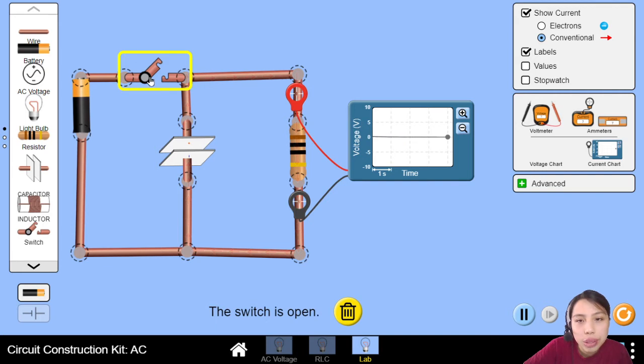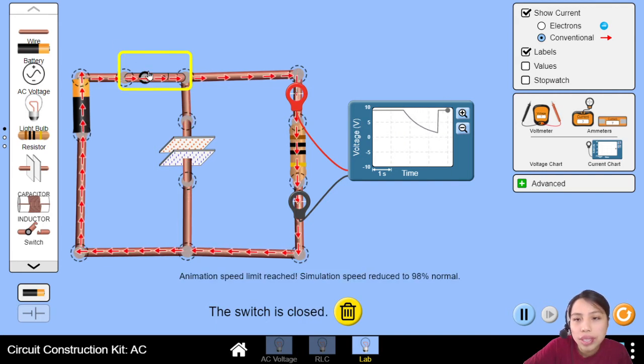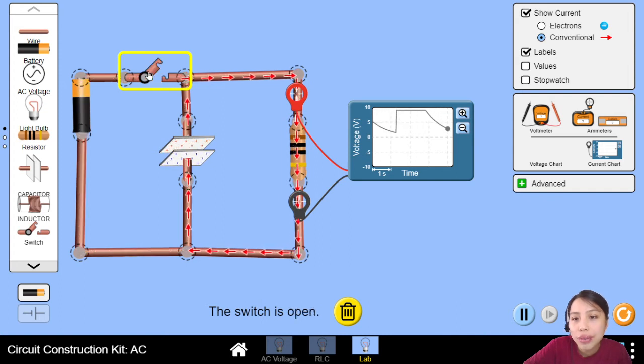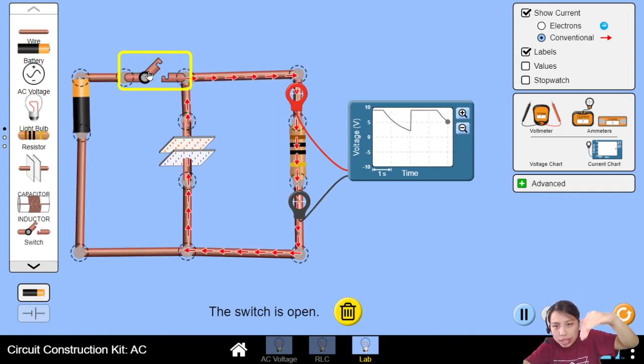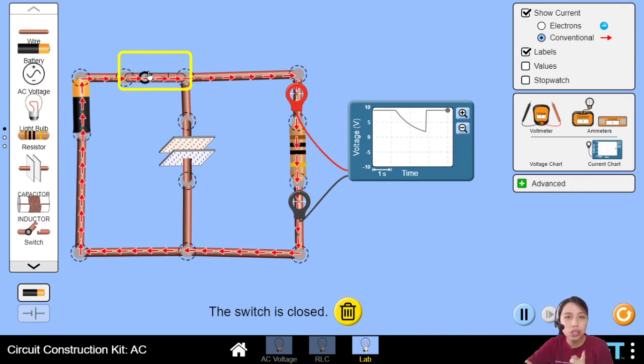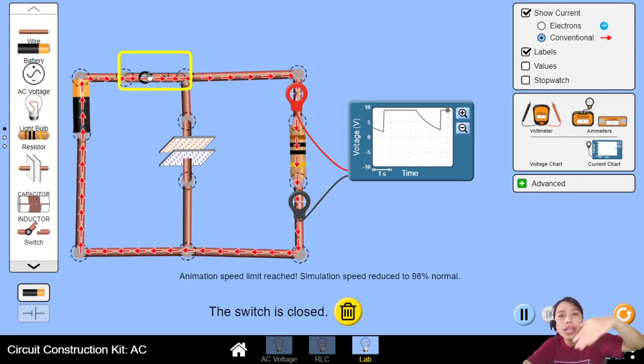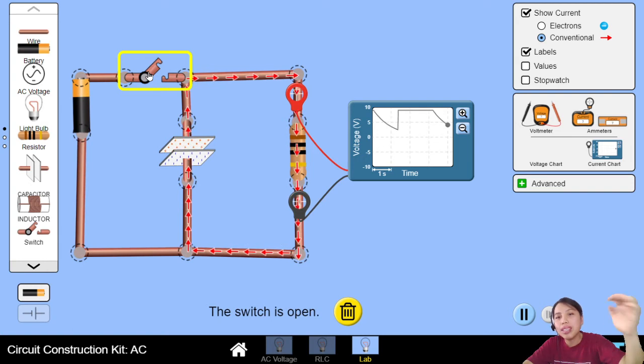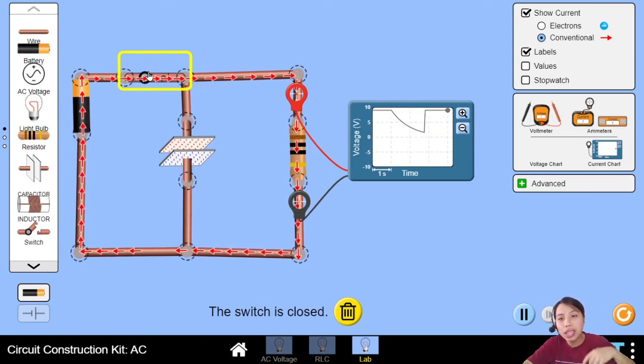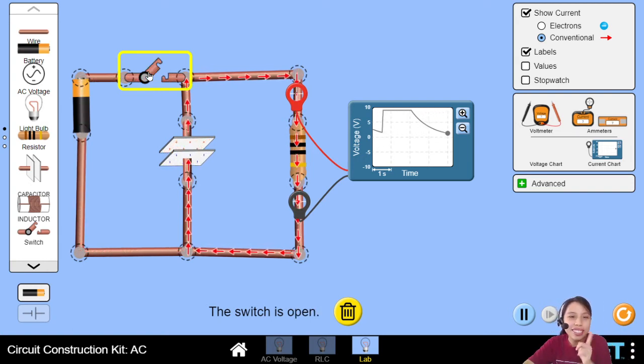Now, if you see, I do the on-off pulse, look at the CRO here. What do you see? It's not square waves anymore, but this curve that decreases, and that is the curve from the discharging capacitor. It's smoothing out the squares. It's making the lumpy thing a little bit smoother. So, this is how it works. Capacitor charge, capacitor discharge through the resistor. So the capacitor is adding like a cushion to store energy and discharge energy as we need it to. And that's called smoothing in action.